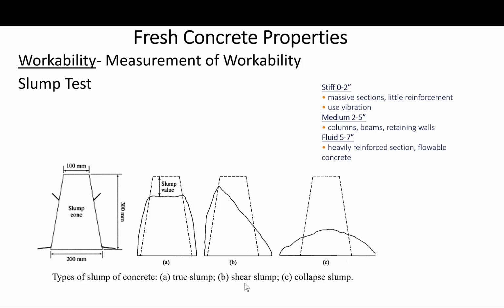An alarm will sound when I see shear slump, which is not often, by the way, just to be fair. But right away you should be alert. That means it's not suitable for placement. Or, as I said, normal mixes are sometimes found to display shear slump, and again you have to repeat the test or look into the specifics of the mix to make sure it is suitable.